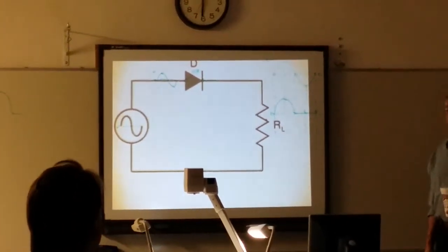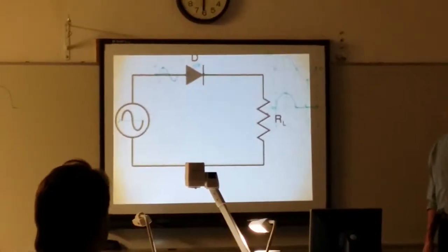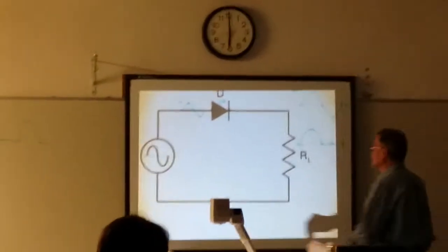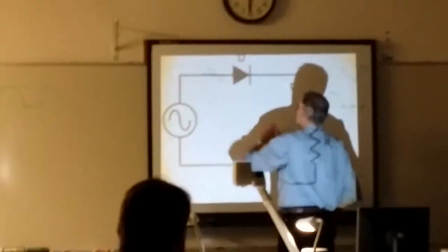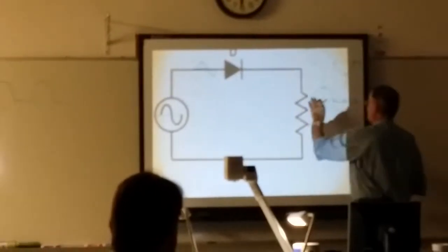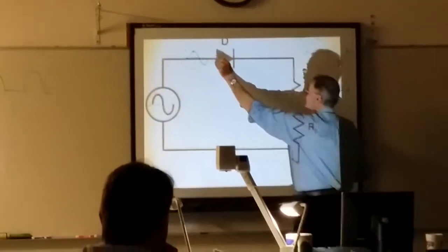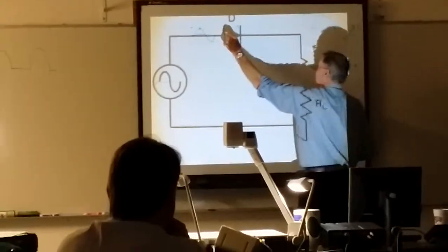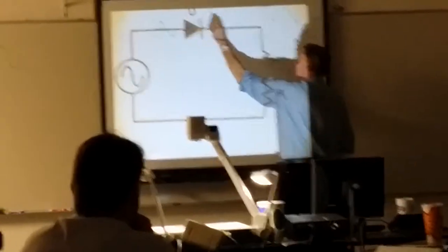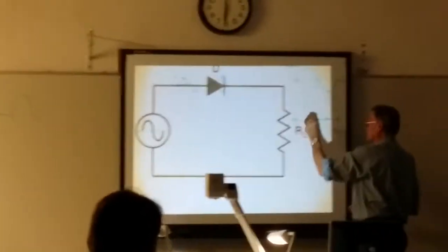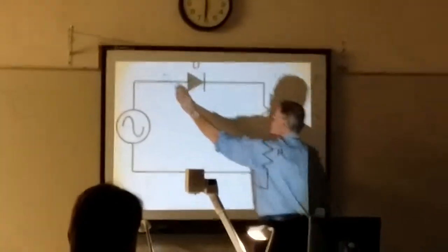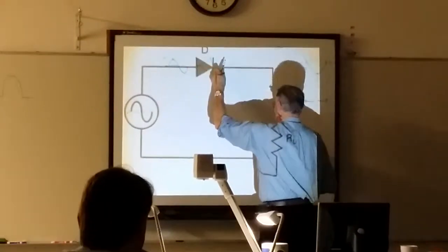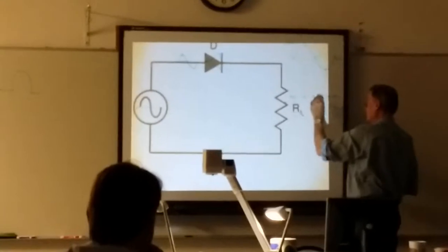So if you turn the diode around, it would do the same thing, just on the negative cycle, right? Yes. If you turn the diode around, so this is now the cathode, when it's positive, the anode is going to be negative with respect to the cathode, so it's off and you get a 0. Then when this goes negative, it's on, the anode is positive, and that negative would appear there.